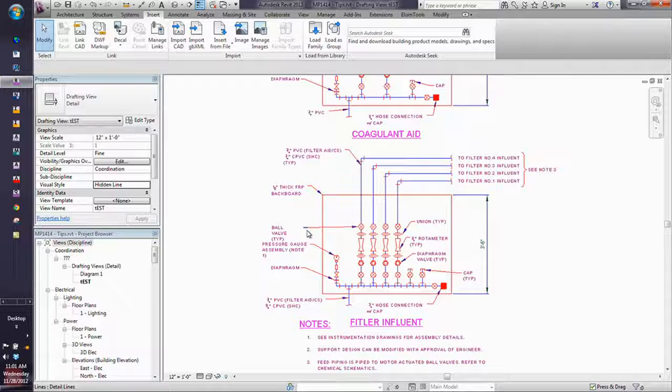This one actually was already exploded, yeah. This was one of his drawings. I've already fussed at him about not using leaders. But you get the idea in here. If I've already got the line style in there, I can use that to match the layer, and life is good. I don't have to worry about them being different. That saved us a ton of time in making sure that our projects look the same in AutoCAD and in Revit, in both places.